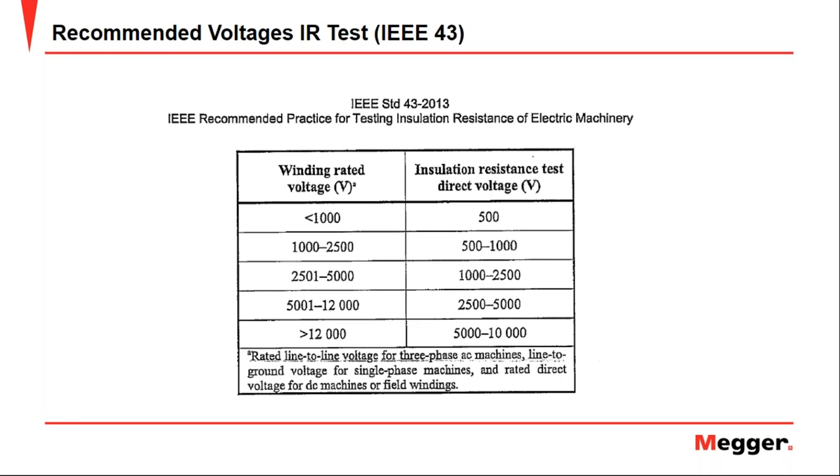Okay, this equipment can do very particular tests. We can do an insulation resistance test phase to ground. We can do an insulation resistance test between phases, between two phases, and we can do the insulation resistance test between the three phases.